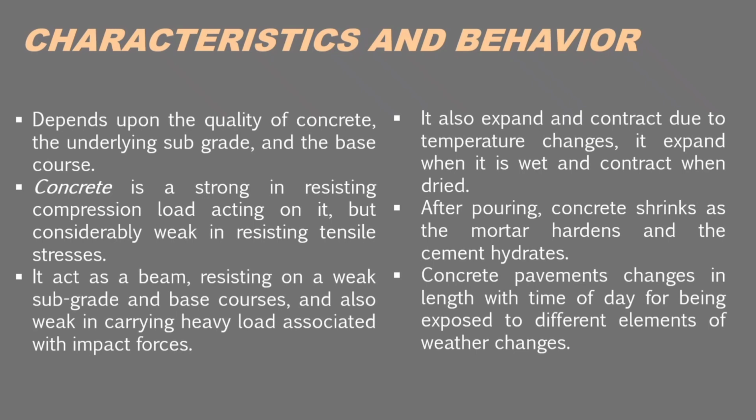It expands when it is wet and contracts when dried. After pouring, concrete shrinks as the mortar hardens and the cement hydrates. Concrete pavements change in length with the time of day, being exposed to different elements of weather changes.